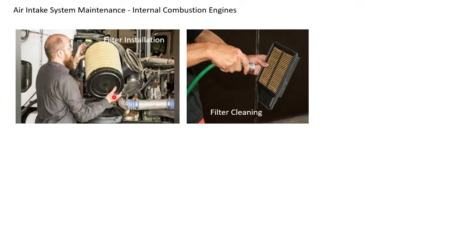And it is advisable to, once you clean this element, rotate 120 degrees and place the filter. So if this is in this position, then just rotate 120 degrees, and do that again. Again clean when the indicator comes. Like this, it is recommended to clean a maximum of 3 times for any paper element. Then afterwards you have to throw the filter and use a new filter.